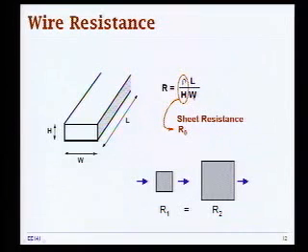Because if you assume that local resistances are scaling in the same way, basically that L and W scale in the same way, that the wire length also tracks the scaling of technology and the scaling of wire width, then if you keep this height constant, you have approximately constant resistance as you scale technology. If you start scaling down this H, then your resistance increases and you're in trouble. So you don't want to do that.